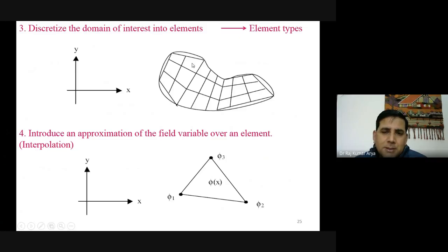Those who work in CFD, Fluent and all this, do a lot of work in discretizing the mesh. Because once you have not generated a proper mesh size, you will unnecessarily end up with n number of equations which you don't need. So discretization is done very carefully, just like I told you: wherever change is not much, you can take a bigger mesh.